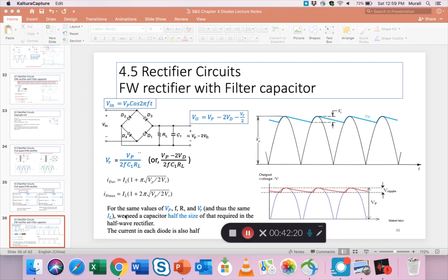We generally deal with capacitors in the microfarads, but once you start getting into the millifarads and so on, larger capacitors can be expensive. So it may be cheaper to create a bridge with 4 diodes and make a full wave bridge instead of a half wave with just one diode. So there's a trade-off in cost. Okay, so you should be aware of that.